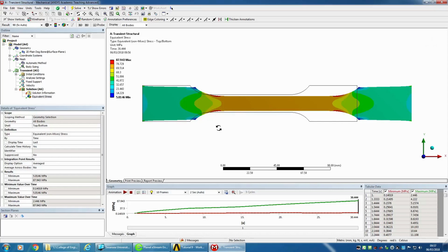And all of this extra gubbins and mesh that we had on the tabs of the sample show the convergence of the stress flow along the tensile test bar. But it might make absolutely no difference to the deformation at any point along here, which is meant to be pretty even. And also, as you can see, it did take quite a long time. That was just a 2D problem, and we could have been here probably for another 20 minutes waiting for it to get to the point where it actually goes past the yield and breaks. Well, it's gone past yield already, but to the actual point where it breaks.